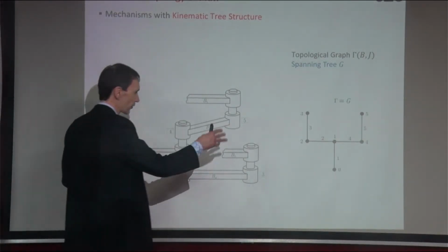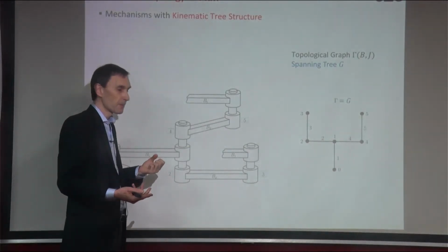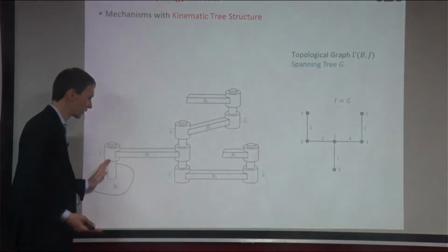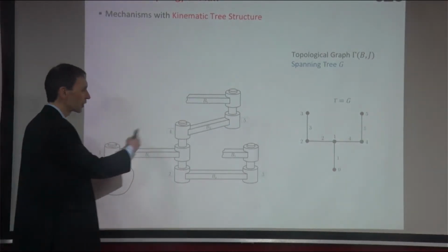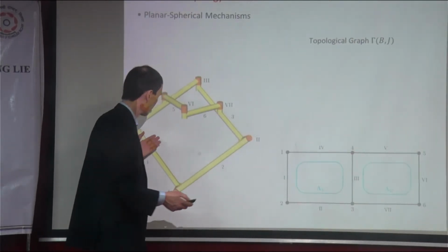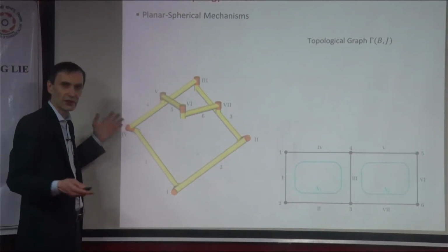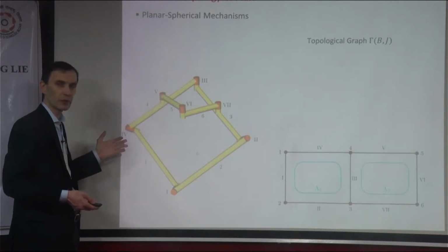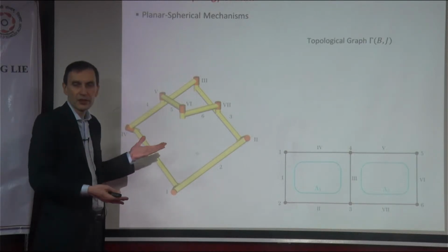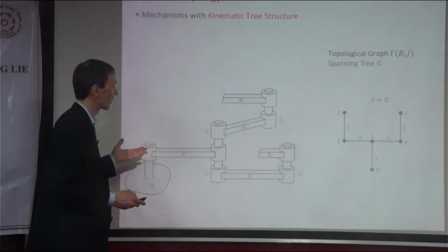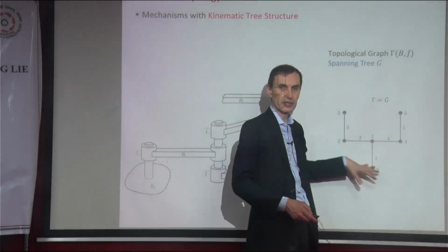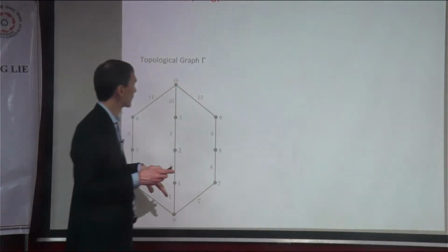So what I would like to say is that at some point you will have to say which link, which body and which joint comes before another joint in order to actually compute the kinematics. Now, if you have a closed loop system, for example this one, that's not easy. I mean, it's not even just not easy, it's not possible, because what's the predecessor? What's the successor here? It's actually not possible to say. But what you have to do is to introduce this kind of tree structure, even for the closed loop systems. And that goes like this.